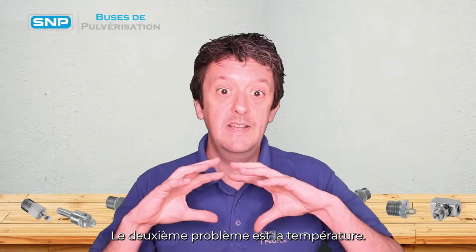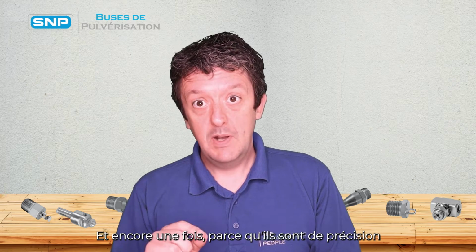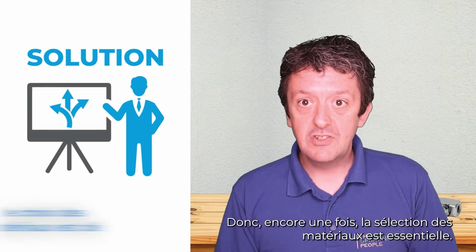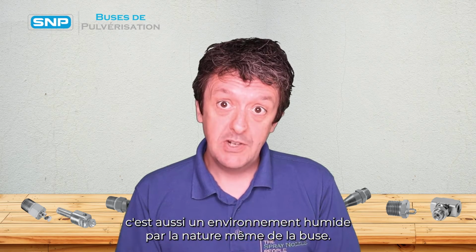The second problem is temperature. If the environment is too hot for the spray nozzle, then that can cause some deformations within the spray nozzle, and again, because they're precision components, only small deformations can cause big problems with the spray. So again, material selection here is key. We also need to remember that if they're spraying in a hot environment, it's also a wet environment by the very nature of the nozzle.